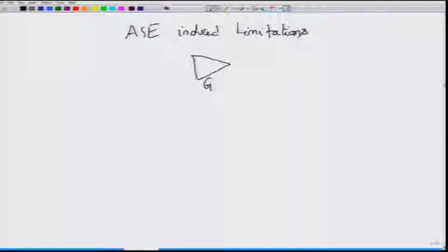One, it is the gain of the amplifier, which means that if at the input terminals of the amplifier we have an optical power of P in, at the output terminals of the amplifier we get a power which is G times P in. As we said, optical amplifiers, or any other amplifier for that matter, are not going to be ideal amplifiers, in the sense that in addition to this signal there would also be ASE noise.